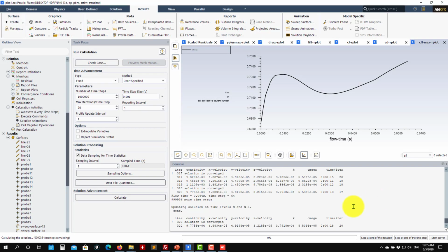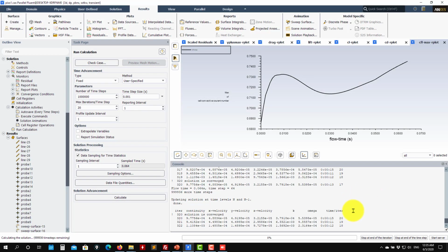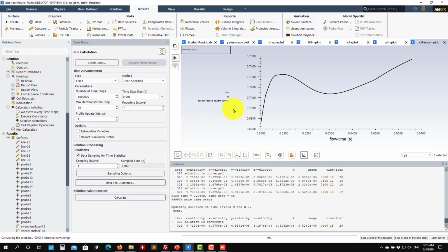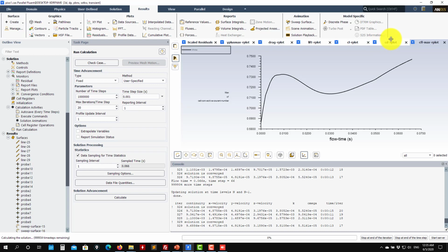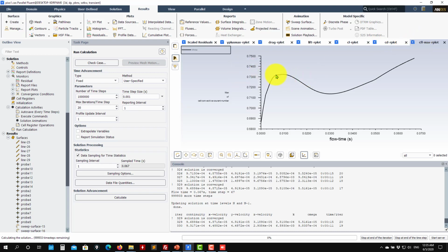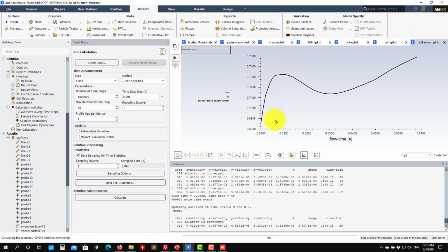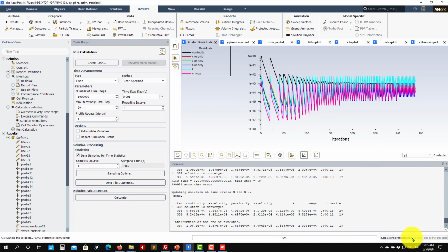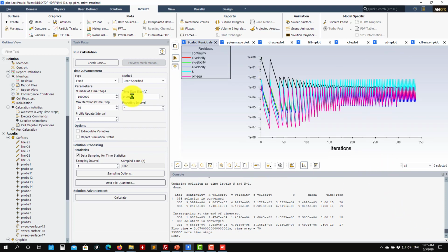Okay, we're back. So see that after a while, it's taking just 4 iterations to converge. So this is ideal. This is what you should aim for. However, you see that your CFL is 0.7, so you can still increase. So let's do some experiment. Let me stop here, and let me double this number here.